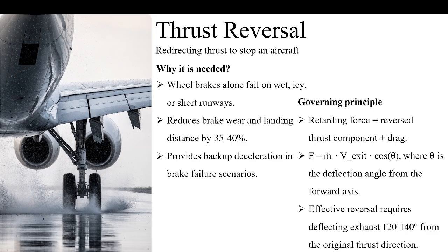Thrust reversal is needed when the wheel brakes alone fail on wet, icy or short runways. It reduces brake wear and tear, and reduces the landing distance by 35 to 40 percent. It provides backup deceleration in brake failure scenarios.